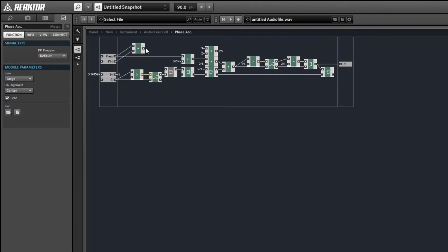So when we add it to the frequency, we're not guaranteed to end up with a positive number. And what that can mean is that sometimes we'll end up adding negative values to our phase accumulator. And this isn't a big problem, but we're not currently set up to deal with this. Like I've been saying, we want to keep the phase output equal to a value between negative n and positive n. And we're not checking at the moment to see if we ever go below negative n.